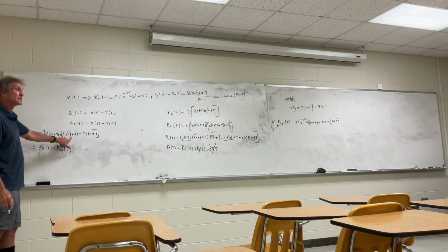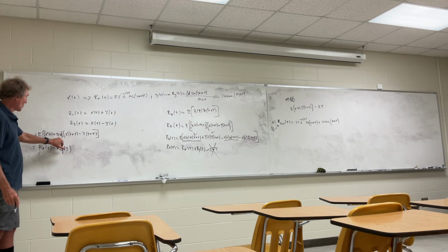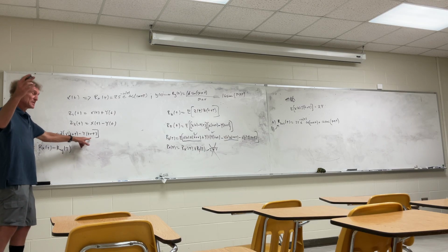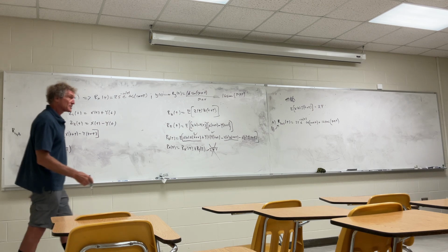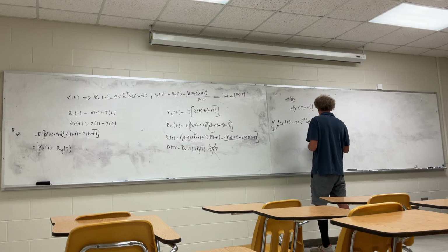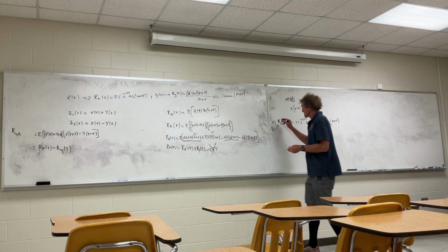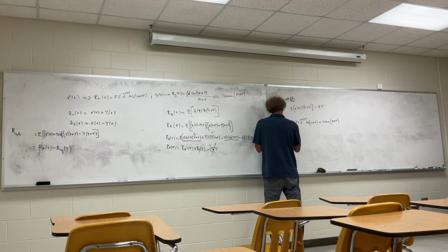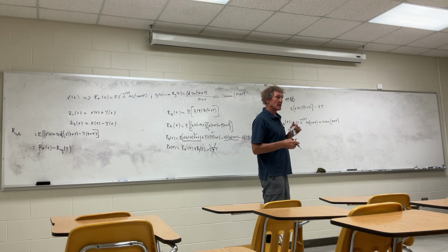Now we get into the cross terms. What about this times this? Y of t times x of t plus tau. The expected value of this would be the mean value of x, mean value of y, right? Which is 0. How about x of t times minus y of t plus tau? Expected value? 0. In other words, this is the answer, R of Z1 comma Z2. Isn't that it? Take a look, make sure.